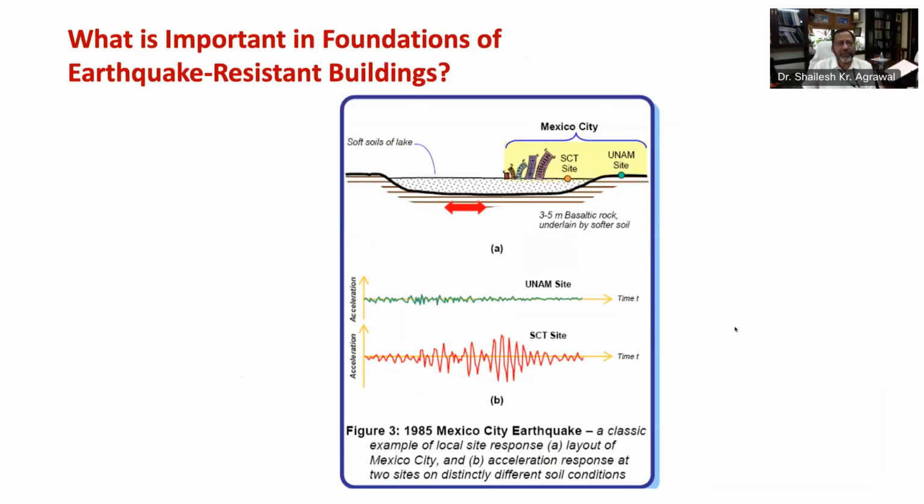Concepts of foundation engineering like bearing capacity, settlement criteria are also relevant in earthquake resistant buildings. Thorough geotechnical investigations at the site are a must for design projects. In addition to traditional standard and cone penetration tests, other in situ tests such as shear velocity test and pressure meter test may also be performed while designing earthquake resistant structures.